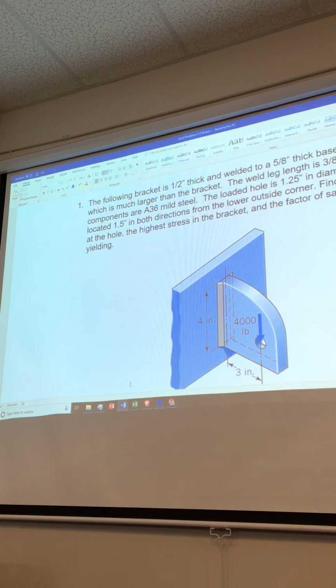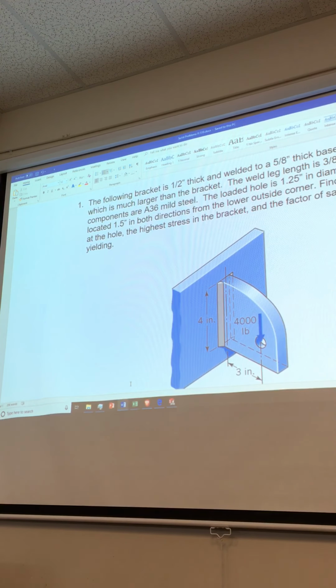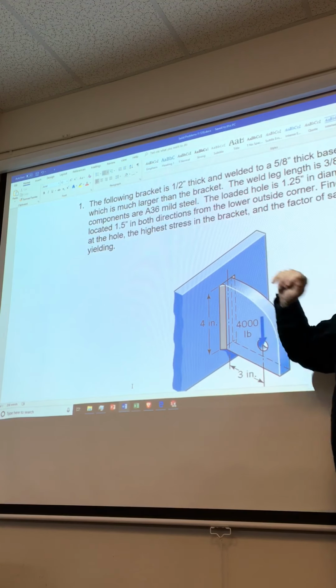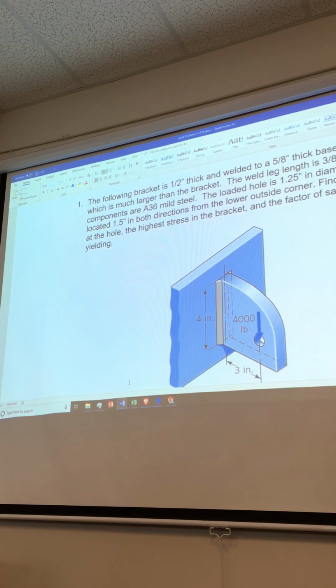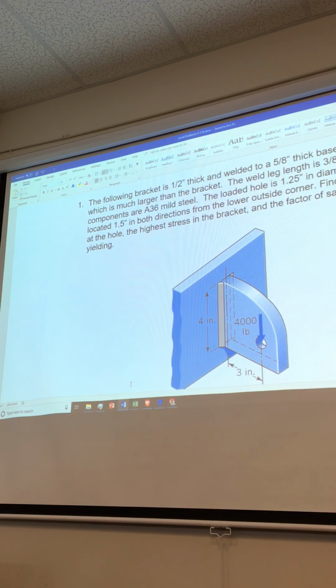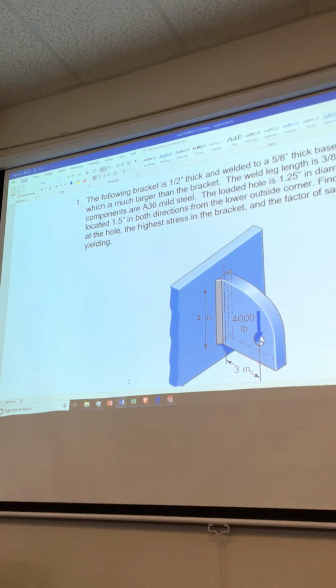Right. Two pieces welded together. Now, there's an interesting question of, we're assuming that it's welded all the way through the center. Well, 1/2 inch, yeah, you can grind it now. And we can get a full penetration weld. It's called a full penetration weld, not a full strength weld. It's quite a bit more expensive to do because you have to basically grind enough room to get the weld all the way into the center there. But, and it may or may not be a real good assumption, right? Okay. So if it's not a real good assumption, then